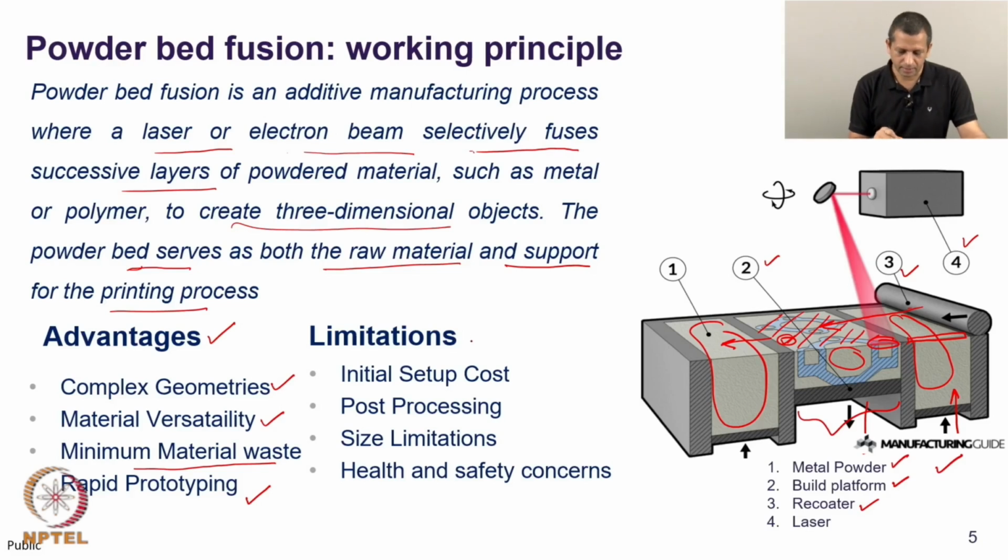However, there are some limitations as well. It takes enormous time and effort and investment to create a setup so that it is ready for building a sensible part of the desired quality. So, there is some cost involved in it. It definitely takes some post processing. You have seen already that there is some extra powder particles stuck around the geometry. Those particles need to be removed, and sometimes there are some support structures of the same material which are unwanted in the application. Those structures need to be removed.